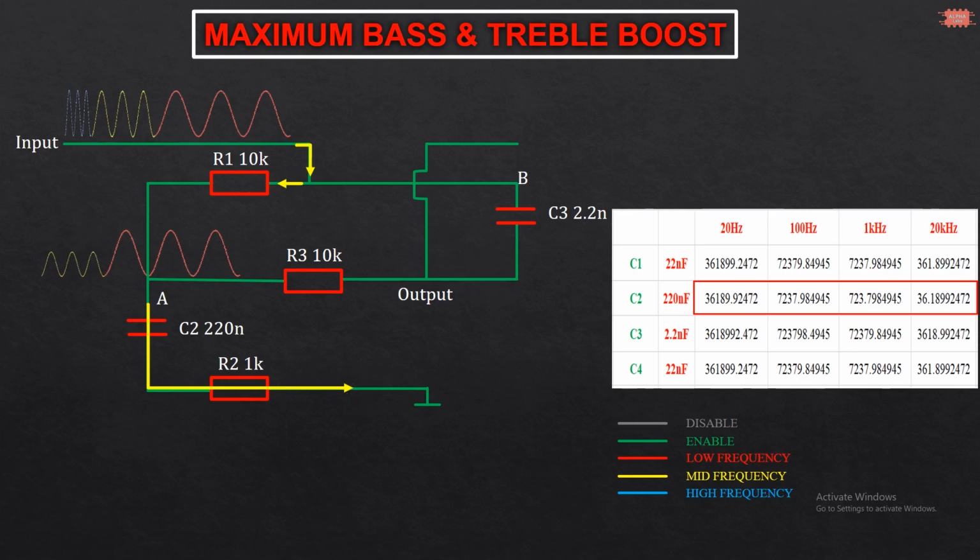The yellow signal has mid-frequency, so that, its amplitude is decreased. The resistor R2 in series with capacitor C2 prevents the attenuation of the mid-band frequencies exceeding about 20 dB. The remaining signals go to output via R3, so that, the bass direction changes from full bandwidth into low amplitude with mid-frequency and full bass frequency.